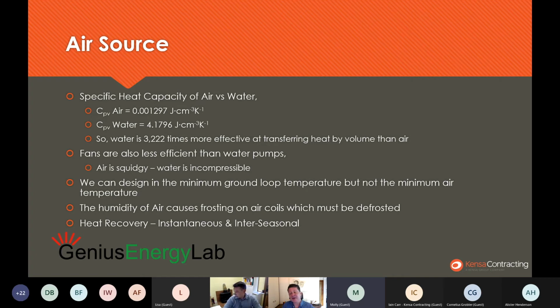Yeah, I mean, if you've got a swimming pool that's only used in the summer when the air's warm, then actually air source is a really good solution for it. And also designing ground loops for swimming pools can be a problem because, you know, there's another name for a swimming pool. It's a cooling tower. It just gets rid of heat. It's brilliant at it. So designing ground loops, because ground loops are a finite resource, we'll talk about that next time, ground loops need to be designed quite carefully for swimming pools. So it's a good point, Duncan.